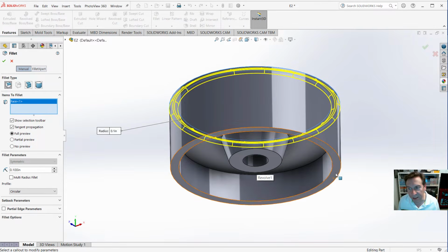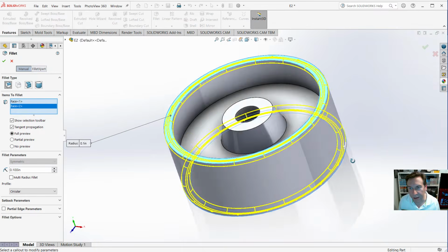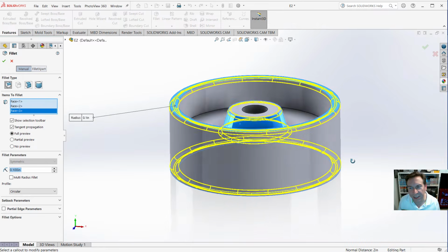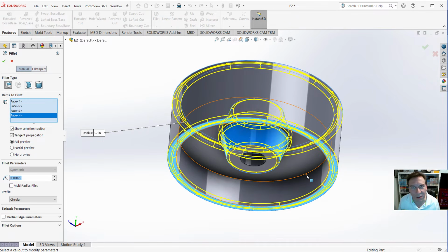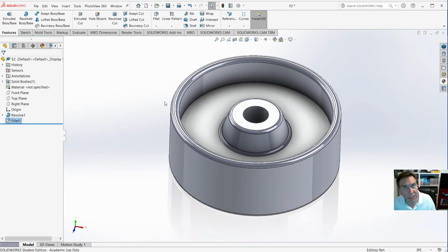Now go ahead and select this face here, and let's bring her back down, and let's go ahead and select this face here, and I should have left it on the other side. I forgot, but go ahead and select that face down there too, and hit the green check. Alright, so faces are very nice. They just fill out the entire topology, which is explained in exercise 1.